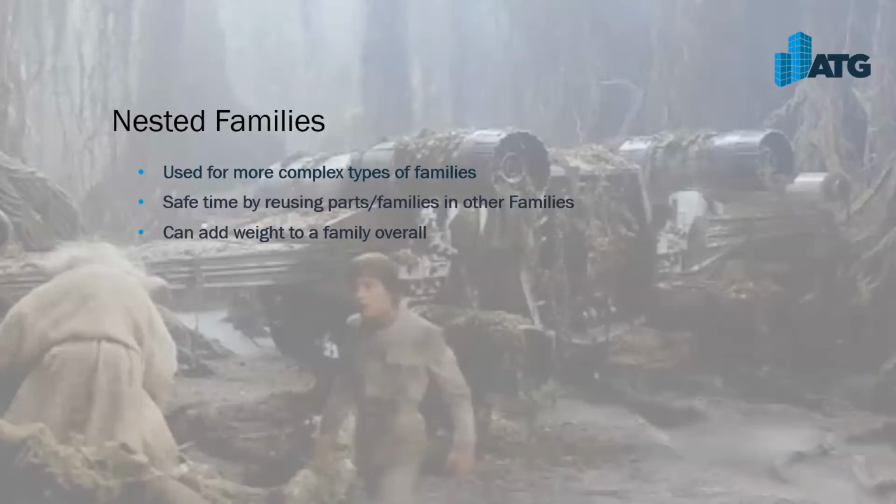The thing that you've got to be aware of is that it can add weight to a family overall. So that family size can really increase as you go in and add nested families. So be very careful with those. Make sure that you're purging all the unnecessary information that is in the nested families before you start bringing them into a collection. We want to kind of shrink wrap those families as much as possible.